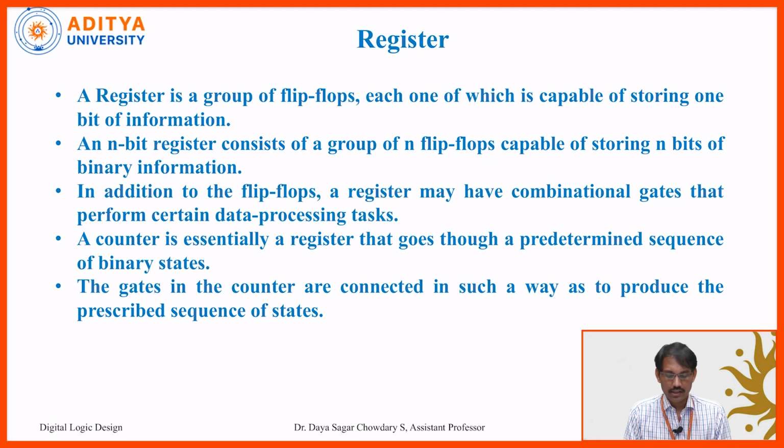Coming to the registers, a register is a group of flip-flops, each one of which is capable of storing one bit of information. Flip-flops are the basic building blocks for the register. Each flip-flop can store only one bit of data, either 1 or 0 digitally. So one flip-flop can store a binary bit, either 1 or 0.